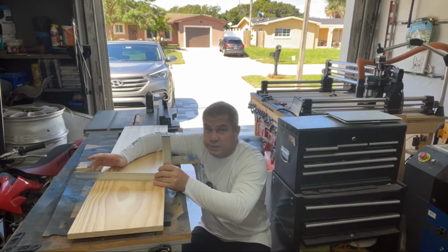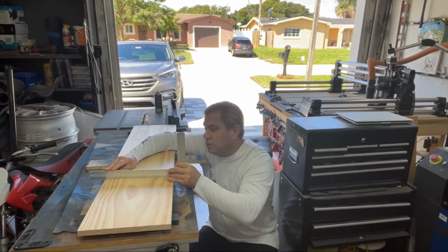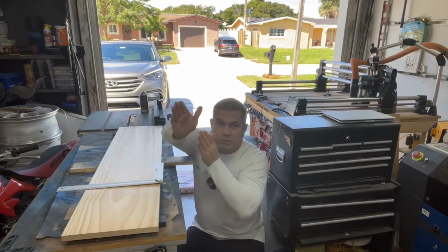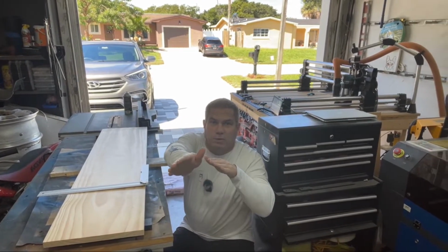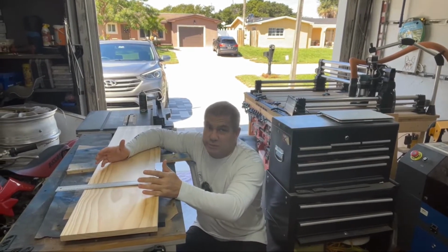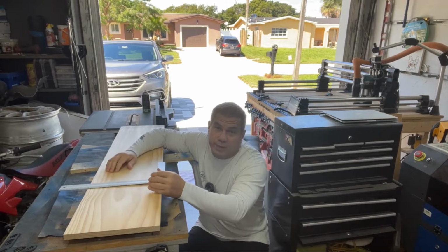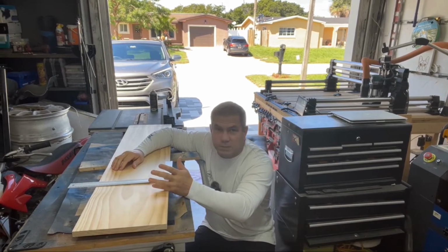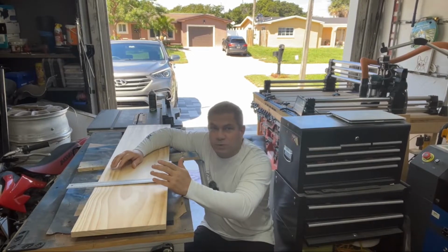What we didn't go over in the box store, I tried to, but people were looking at me strange, and I'm not that type of guy. What you want to check for is twist in the board, okay? You want to make sure your board is perfectly aligned. You don't want your board to angle or twist. Big box stores usually sell construction lumber, so they don't care. These framers are going to put it up and walk away and have a nice day. But we're trying to do a nice little project here, so you want to check for twist.